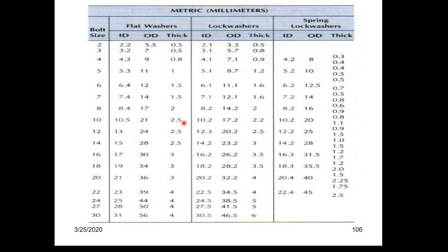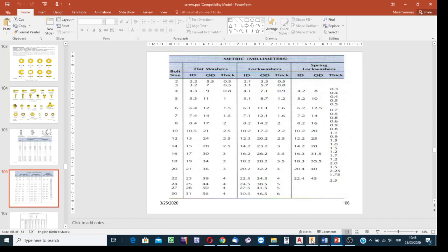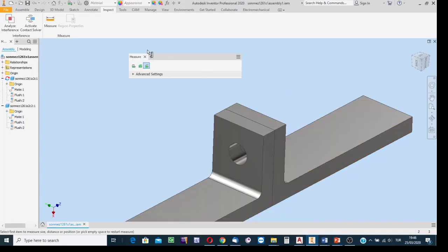Okay. And also it's a good practice, when we tightly screw the bolt against the nut, that beyond the surface of the nut there should be a few more millimeters of extension. Okay, so I'm going to consider all of such things in making the selection.